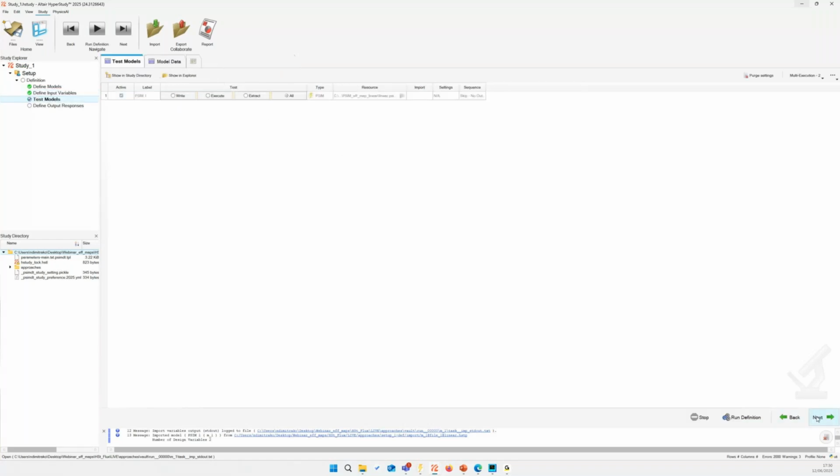Then you click Next, and you click Run Definition. The run definition basically writes and executes the nominal values once, so you can set the outputs you will be reading from HyperStudy. By the way, this webinar is not meant to explain the complete process of automating PSIM HyperStudy to you. We have plenty of material online, and there's also a step-by-step tutorial on how to do this. This is just to show that you can create an efficiency map without writing any scripting. So I haven't written any lines of code until now.